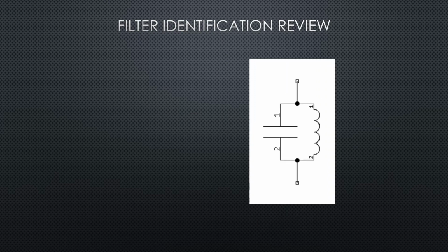Okay, when the inductor and the capacitor, these two reactive components, are wired in parallel at resonance, the way I remember it is product over sum for the impedance. And the sum, the denominator part of that equation, is approaching zero. Remember, the capacitor and the inductor are 180 degrees out of phase, so as they become equal, they subtract from each other.